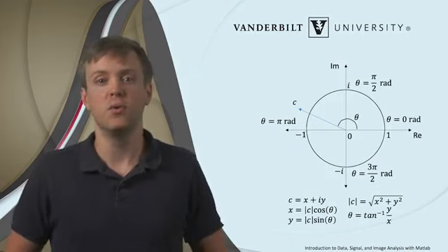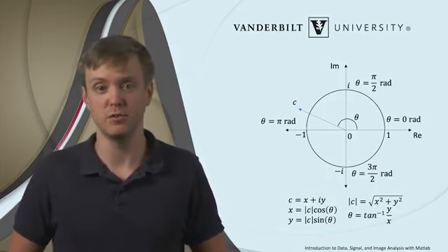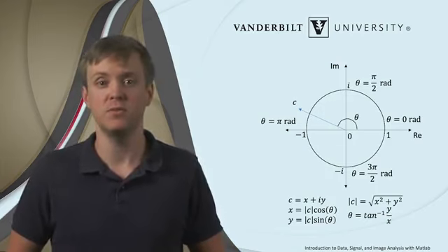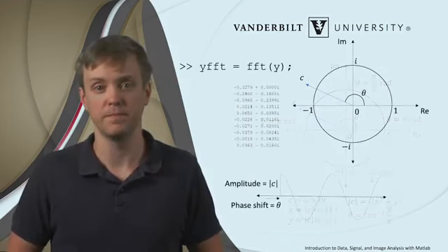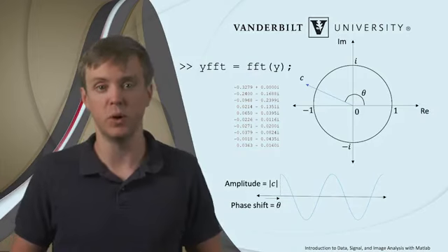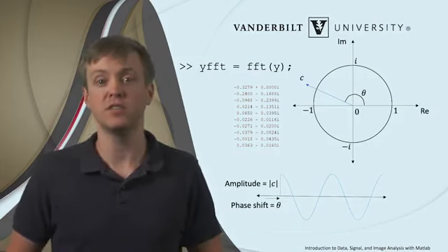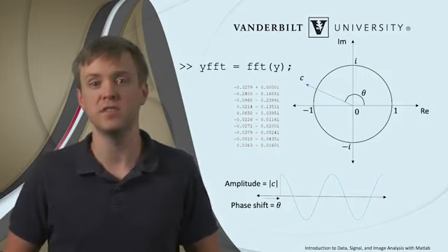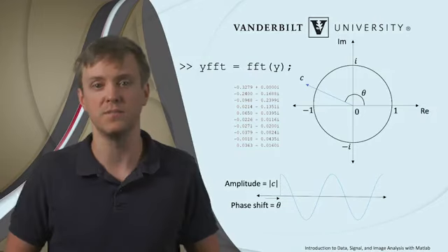Okay, so we have the basics about the general 2D nature of complex numbers. So now we can talk about why we need these 2D numbers with the Fourier transform. For the case of real-valued signals, which is where we will limit our scope, the Fourier transform tells us how to represent the signal as a sum of scaled cosine waves that oscillate at different frequencies.